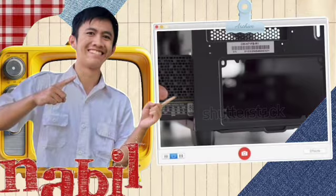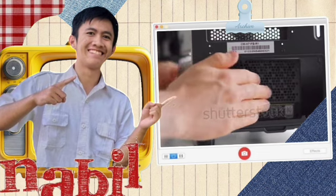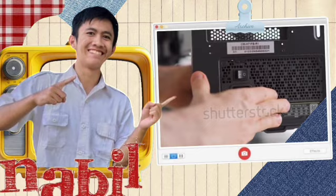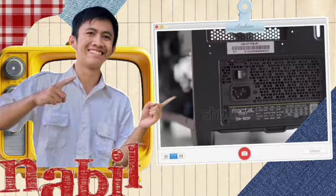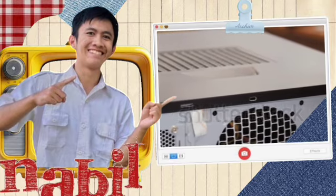Step 7. Installing the power supply. Flip your case so you can access the bottom area. Position the power supply so its fan faces downward if there's a ventilation opening, or upward if not. Slide it into place, line up the screw holes and secure it tightly. Route the major cables through the back for a cleaner build.